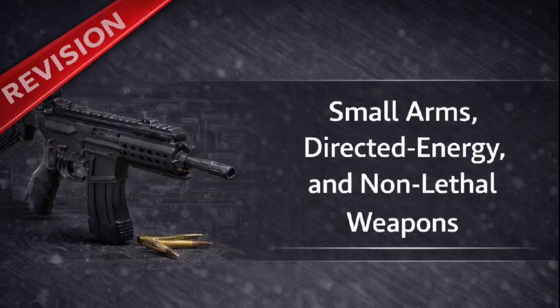This inherent design limitation is why the 9mm carbine machine is such a classic example of this principle. The cartridge is powerful enough to cycle the action, but it's weak enough to be contained by a reasonably sized mass of steel. So simple blowback is really limited to low-powered cartridges. I understand engineers developed variations to apply the principle to slightly higher-powered weapons. Let's analyze the 4 key types. Okay, the first is simple blowback, which is our baseline. It's purely mass and spring resistance, used strictly in low-power weapons like small pistols and submachine guns.